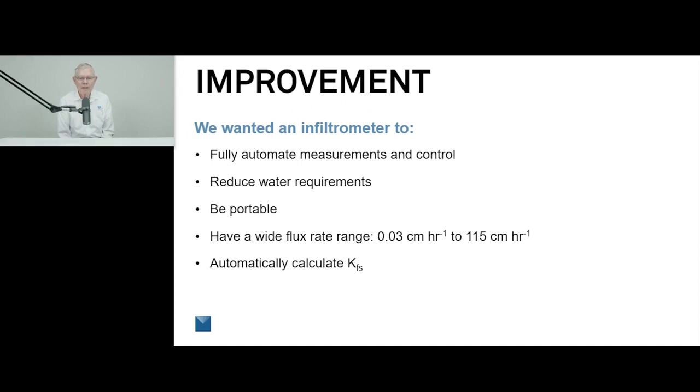So these were the design goals that we had for the Saturo when we started on it. We wanted to fully automate the measurement and control, wanted to reduce water requirements, wanted to make it portable, make it capable of measuring a wide range of hydraulic conductivities, and we wanted it to do the calculations internally.